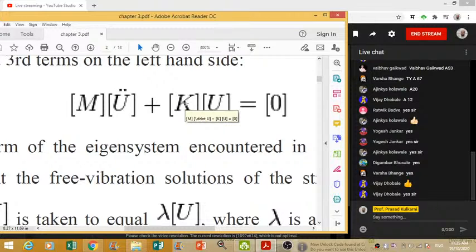How to do modal analysis? Suppose one student has designed a spur gear and the module is calculated as 5. On the basis of the module you draw the spur gear, so you have to draw its CAD model. After drawing the CAD model, you enter the ANSYS software, do its modal analysis, and calculate its natural frequency.